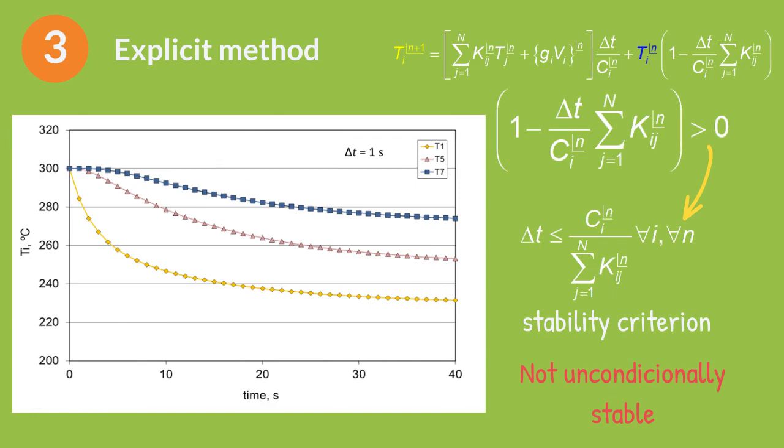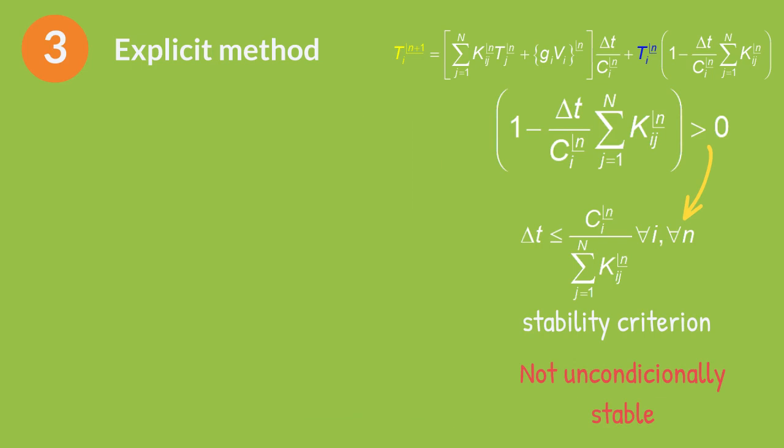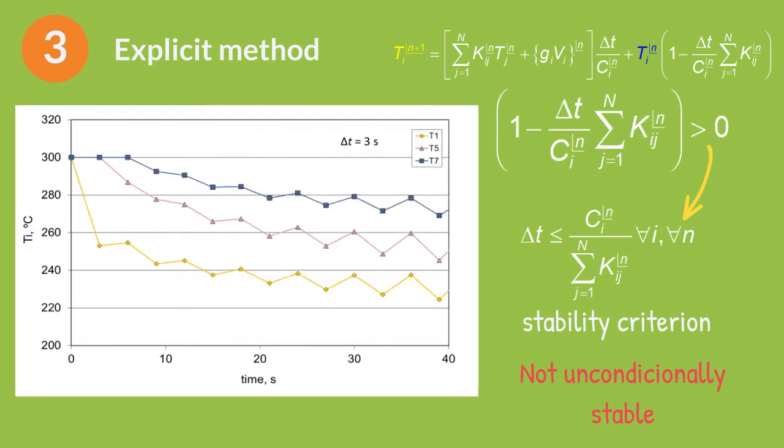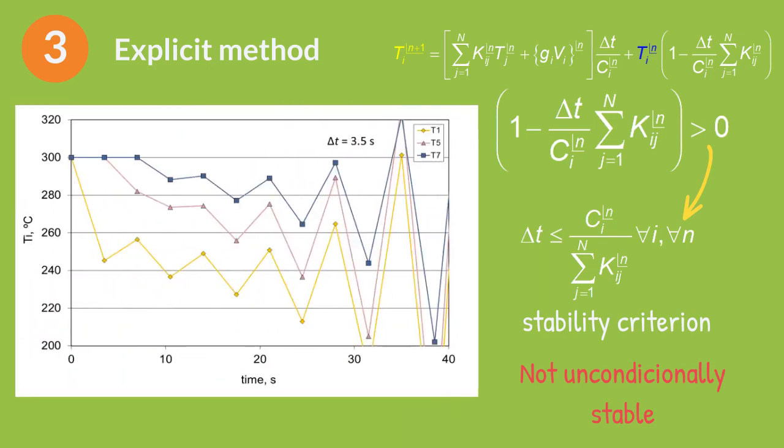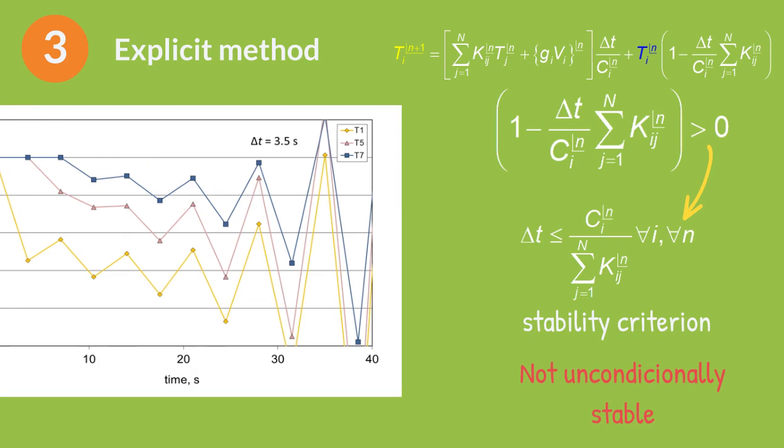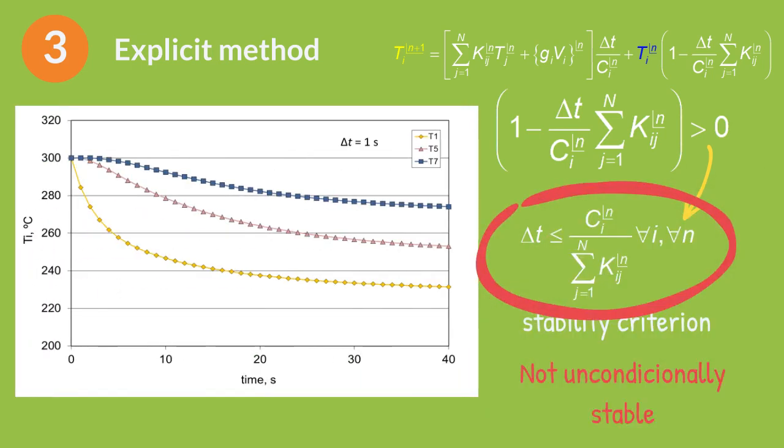In a transient problem, the solution for the nodal temperatures should continuously approach final steady-state values with increasing time. However, with the explicit method, the solution for a delta T higher than the one ensuring stability may be characterized by numerically induced oscillations, which are physically impossible. The oscillations may become unstable, causing the solution to diverge from the actual performance of the system we are simulating. To prevent such erroneous results, the prescribed value of delta T must be maintained below a certain limit.